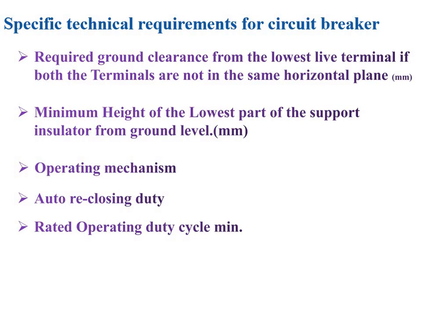So when the fault is there, the circuit breaker contacts open, it will wait for 0.3 seconds, then it will close the contacts. That time of 0.3 seconds is decided generally as per standard, but depending on your requirement you can go for some different time which is practically possible.